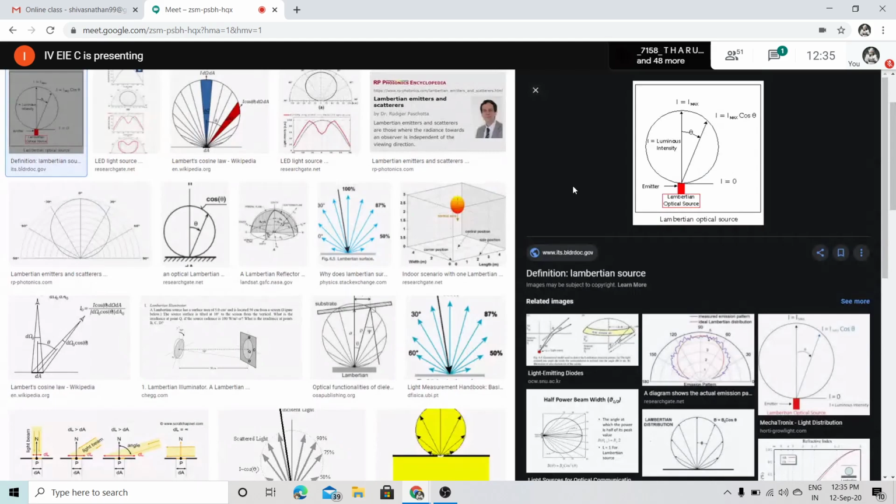Okay, and the disadvantages: the magneto-optic modulator requires a high value of applied magnetic field to have quite a small change in the angle of rotation. Clear? And similarly, the angle of rotation depends upon the wavelength too. So if my wavelength changes, the angle of rotation might also change. So this is the disadvantage that we speak of in magneto-optic modulators.